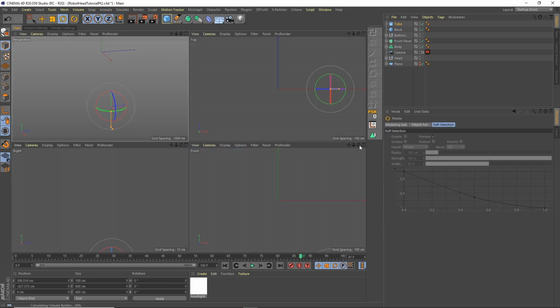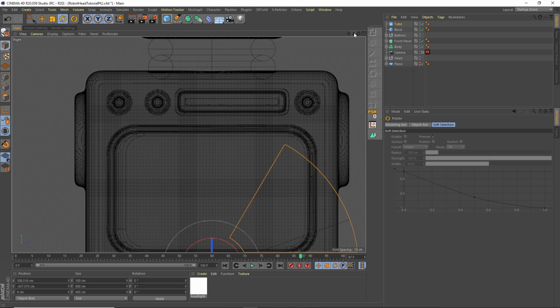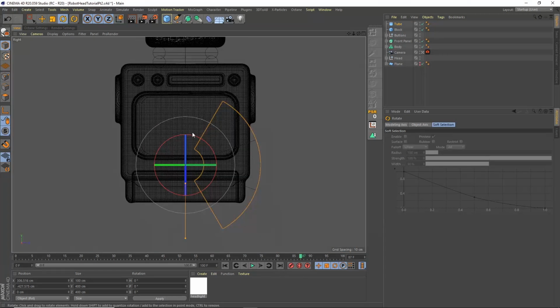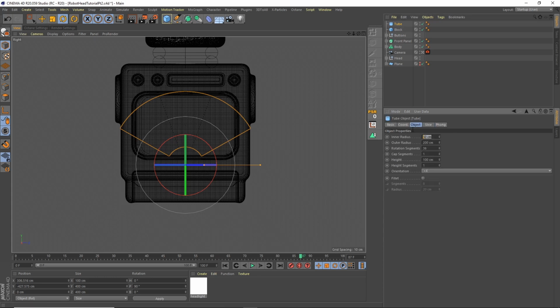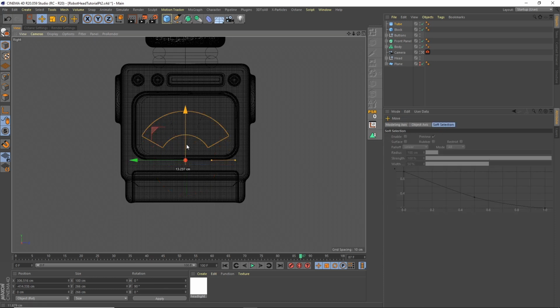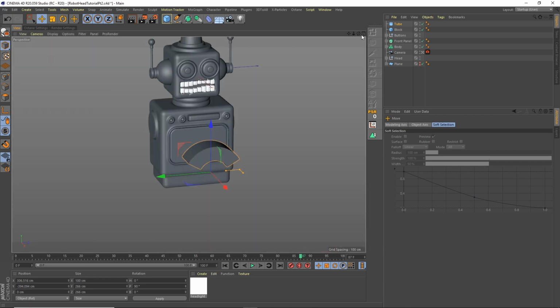And then if I go into that front view, we can rotate it. So let's rotate this by 90 degrees. And then I'm going to change my inner radius to 70 and outer to 133. So now we've got this dial pattern, and we'll go into our front view.